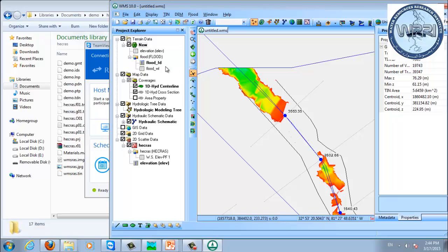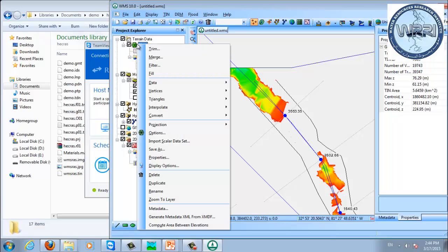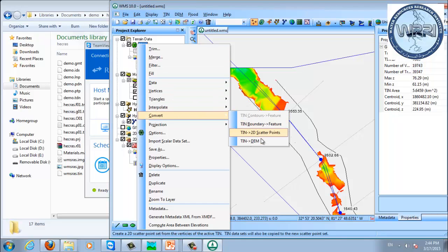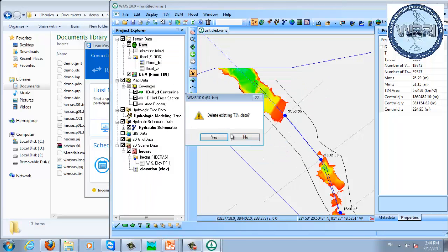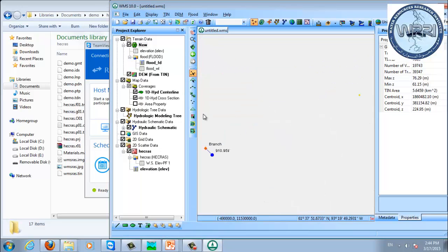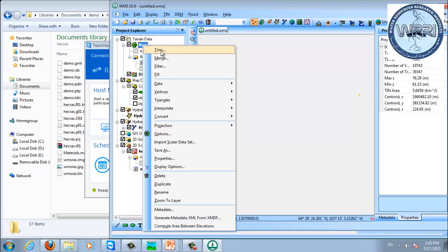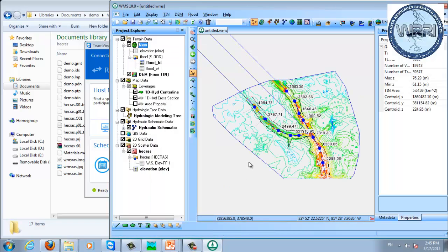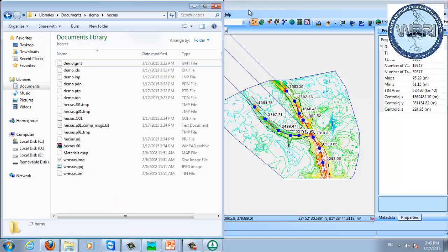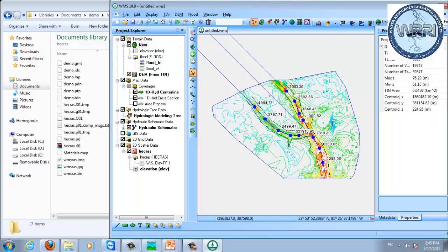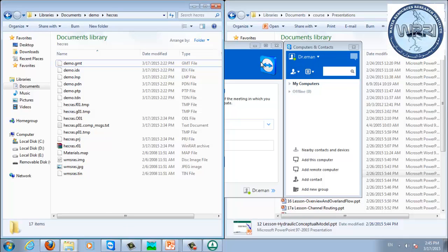But you can convert. If I have a TIN, I can convert the TIN to a DEM. I'm talking about the resolution, the resolution of the DEM or the cross sections. Usually, if you have a channel width like 100 meters, with the DEM it will be 90 meters. So you probably need some survey data for your channel.